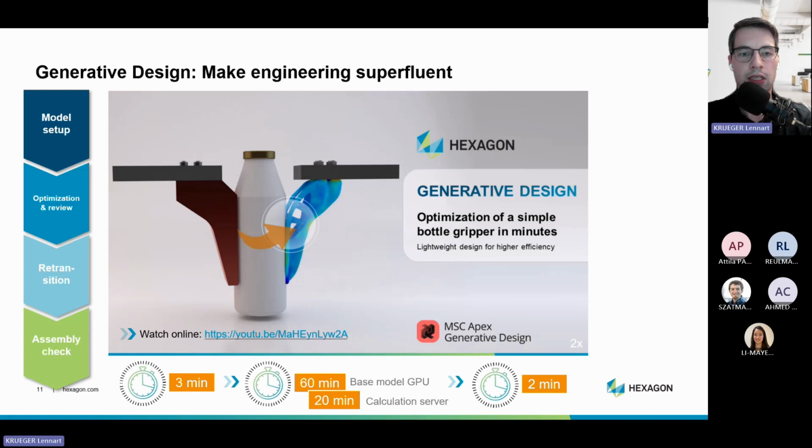As we already have seen, we now can observe the stresses of the part, the von Mises stress or max principal stress, and so on. We can check once again if we have some areas which exceed the desired stress. In most cases, you want to be below the fatigue strength of the part and maybe also including a safety factor. And you can check the displacement of your part under loading condition and the movement.